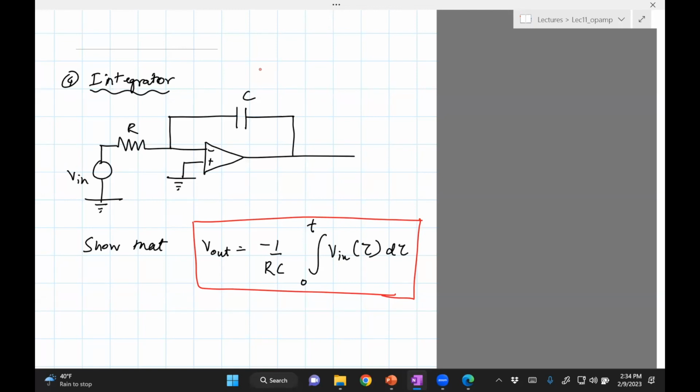Again, one use of this would be if you have, let's see, what sensor gives you a derivative? A velocimeter. I don't know if you know about that. It's basically a sensor which measures linear velocity, not angular, or even a gyroscope is more common. A gyroscope is a sensor which gives you angular speed. So if you take that angular speed as an input and provide it to this Opamp circuit, it will integrate and give you some estimate of the angle. It needs to be zeroed though.